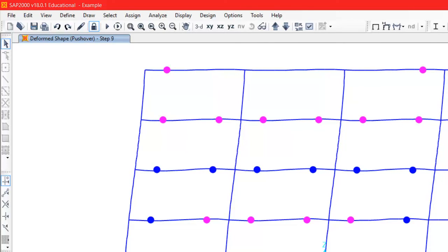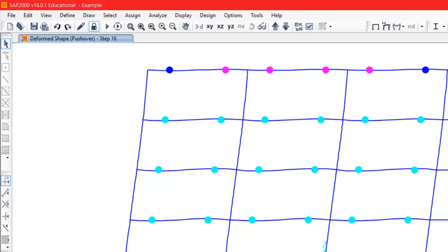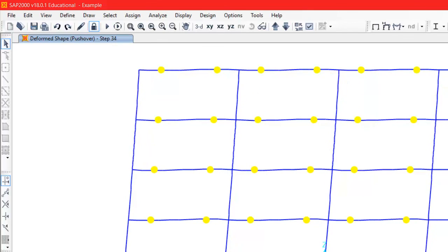I keep going. Now, the lateral drift keeps increasing, but you see it going back. It doesn't mean it's less. It's still more, but it's just because it's adjusting the view. So this point keeps moving. Okay. So I keep going again, and now I have something like a mechanism that will be pushed more and so on. So using those, I can know if I have some acceptance criteria.